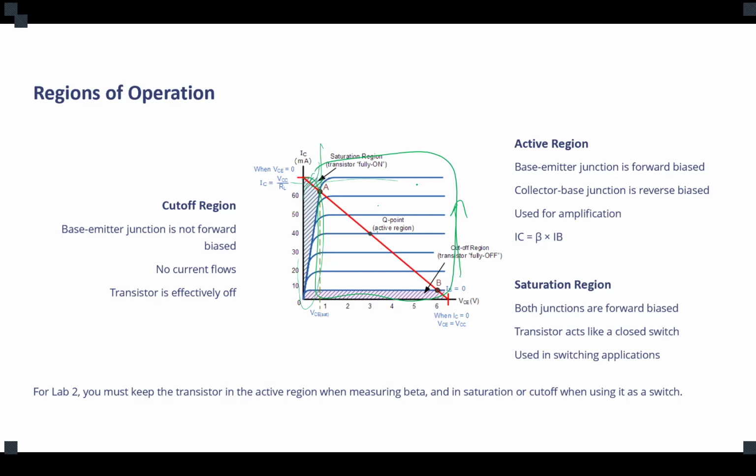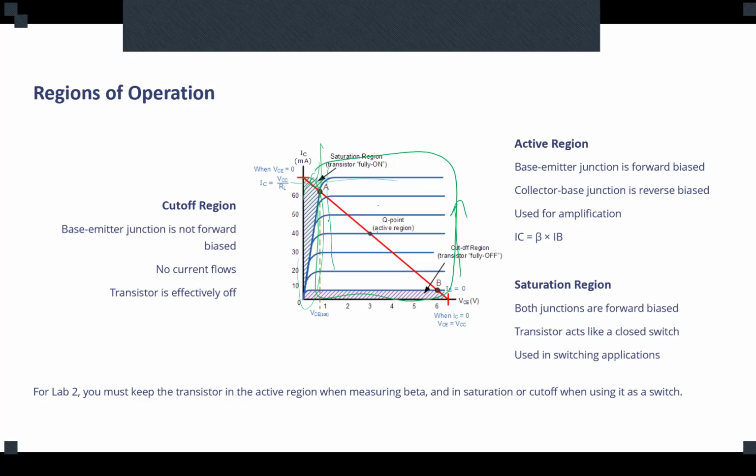Again, we normally use the BJT in an active region, in the region that the collector current is saturated and is constant. In reality, it's not actually constant. There is a slope, but we can neglect that. It's a very low rate of change under the slope, so we can consider it constant. So we use the MOSFET, sorry, the BJT in the active region, and